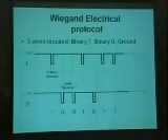So once you swipe your card, what you actually get is the Wiegand electrical protocol. There's basically 3 wires, a data 1 wire, a data 0 wire, and a ground wire. And these tiny little pulses are effectively what you'd see as you swipe the card down through the reader. So you've got your binary 1 here.